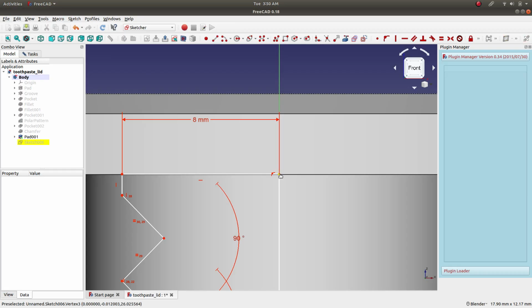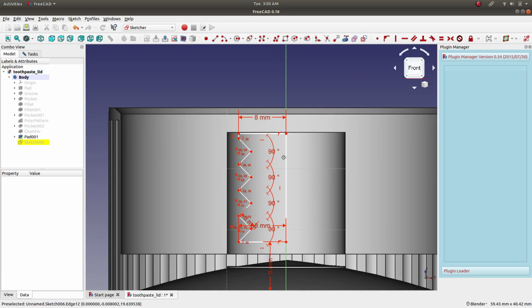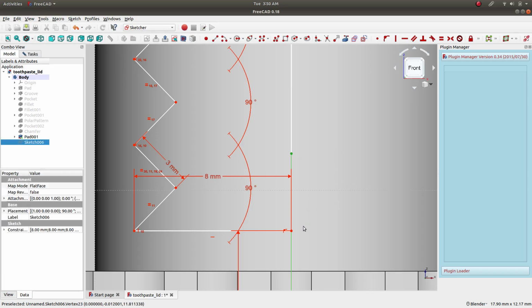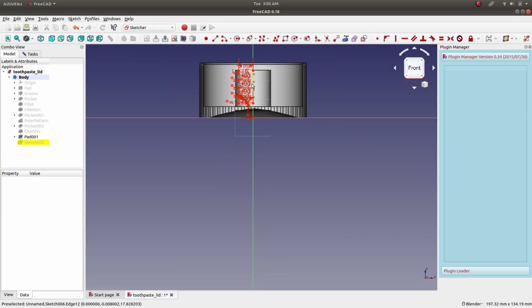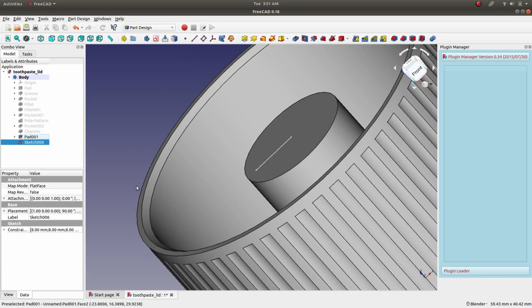Sometimes, if the sketch is not alright, you'll have issues. Yeah, see here our sketch is actually open. This point is not meeting this particular one. Now I think it should be cool. Let's keep a gap. Let's exit our sketch now.